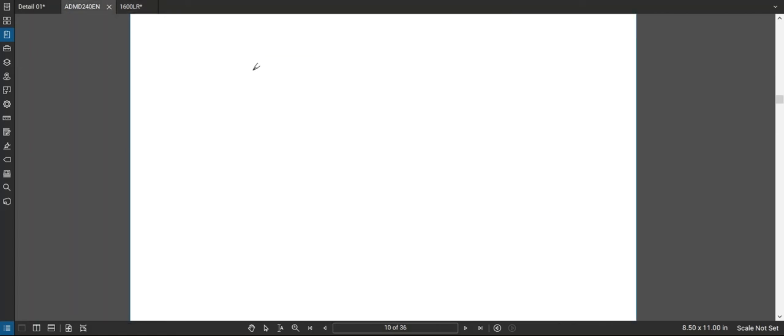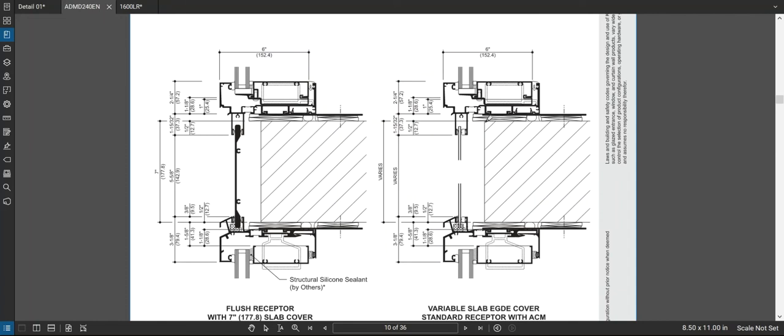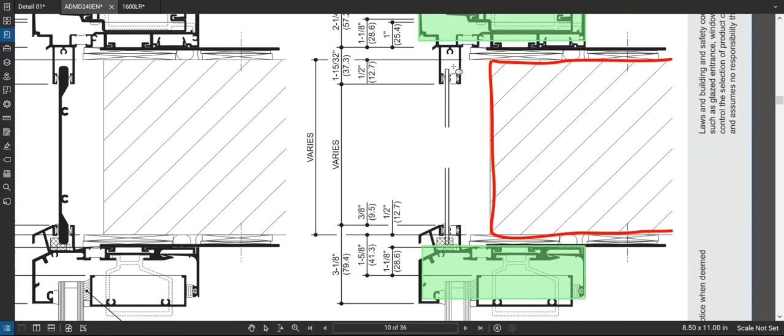And then if we look at a window wall system, the primary difference in this case is that this would be your concrete floor structure. And you'll see that the frame system is, that's the frame there and that's the frame there, it's not outside the structure. It's sitting on the structure, and what happens here is there's a panel that just goes between that frame system.